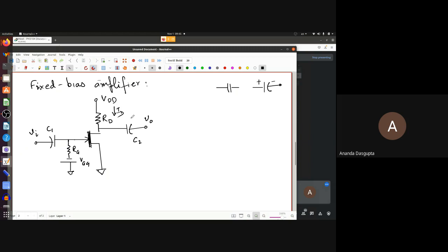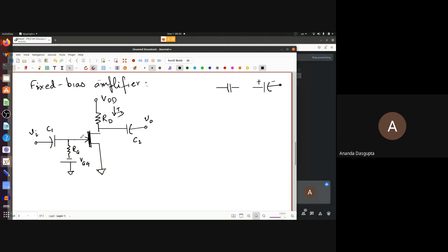We have gone into a high enough frequency regime that the capacitors can be replaced by shorts, but not to such a high frequency that the capacitance between the gate and the channel matters. Remember, the gate P is a highly conducting region, and the N channel is another, separated by a depletion region which has no charge carriers. So it's basically like an insulator between two conductors, exactly what a capacitor is. Any reverse bias PN junction would have some capacitance, but this capacitance will be tiny.